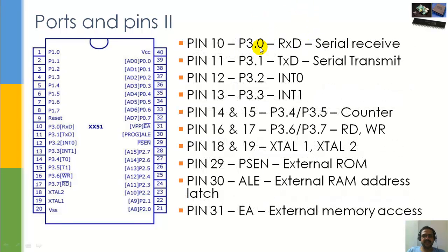These are the other pins that I was talking about. 3.0 is used for serial receive. 3.1 for transmit, INT0, INT1, counter pins 14 and 15, the T0, yeah, I forgot to mention, T0 and T1 are used for counting.